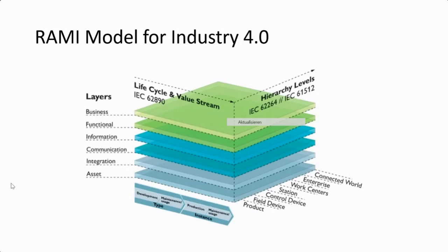You use your asset, you integrate it with the help of an edge controller, and you use a communication protocol like OPC UA or maybe even MQTT, and then you channelize that and send that information to your cloud solutions. Or maybe you avoid that and go directly to the business layer and make business decisions. For example, if the device is not functioning well, you have to pull the plug and finish it off. So this is how you move all the processing to the edge itself.